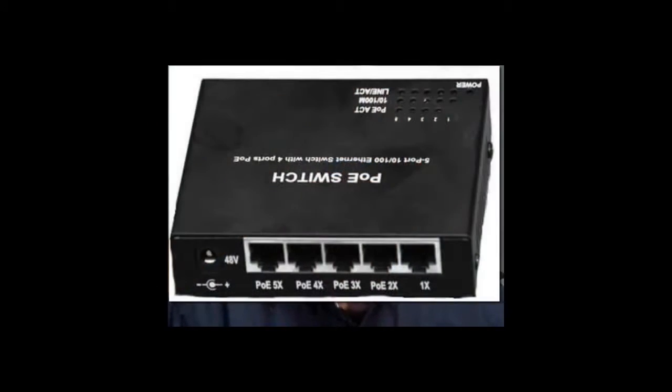So since most of these devices use low voltage, 5 or 12 volts, a means of running the power through the Cat cable has been devised, and appropriately it's called PoE, Power over Ethernet. In these situations, a powered switch or router is used that supports PoE, and the remote device talks to the powered device to specify the voltage it wants. So the power is sent through the two pair of wires that we're not using.